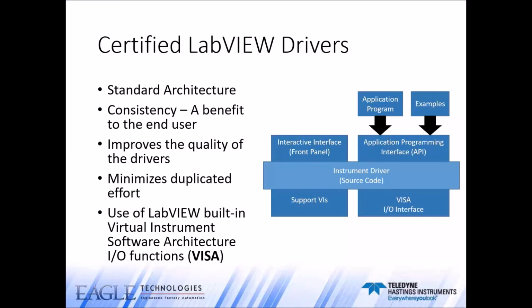The virtual instrument software architecture interface, or VISA, is the set of LabVIEW functions the driver uses to communicate with the instrument hardware. VISA is an established standard instrumentation interface that controls GPIB, USB, serial, and other instrument buses. Support VIs are VIs that you don't intend the end user to access directly. Therefore, support VIs are not part of the instrument driver API.